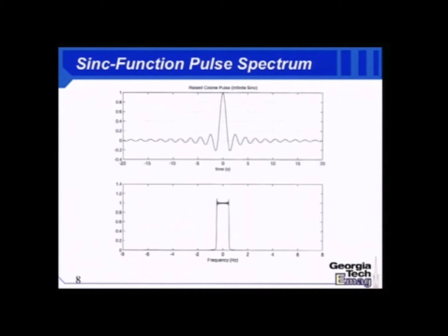of that pulse. Now, I took the Fourier transform, and sure enough, I see a box. I actually see a little bit of rippling at the corners of the square wave, and you can see that it doesn't quite go to 0. In fact, you could see quite a bit of spectral energy if I put this in the logarithmic domain, but I don't think I did for this particular plot. You see just a little bit of curving off.